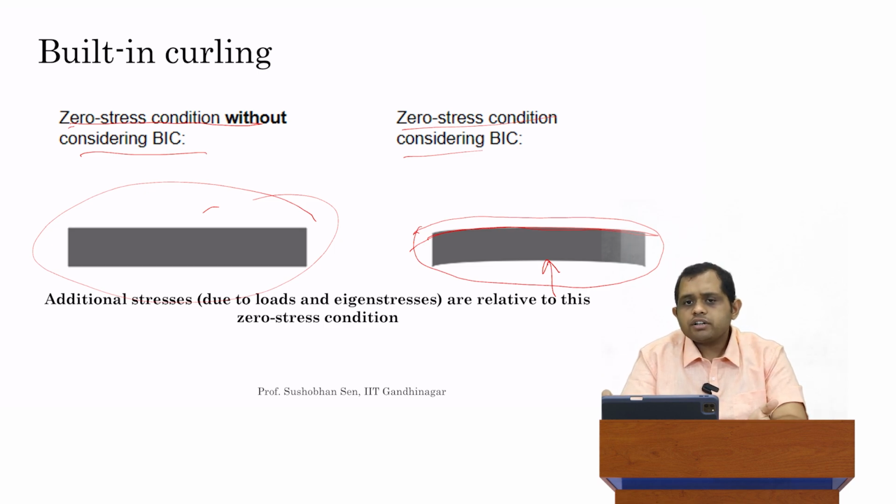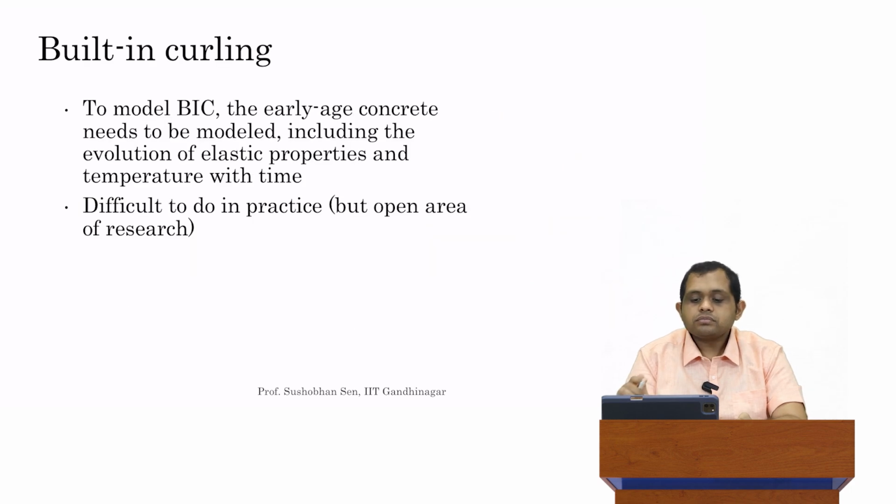But if the concrete is laid during the night, then you can have a different reference condition. It can look like this. So actually figuring out what the reference condition is is quite complicated. I'll talk about that in the next slide. So these additional stresses due to the presence of this have to be taken into account. If we don't consider this, we'll make significant errors in our calculation.